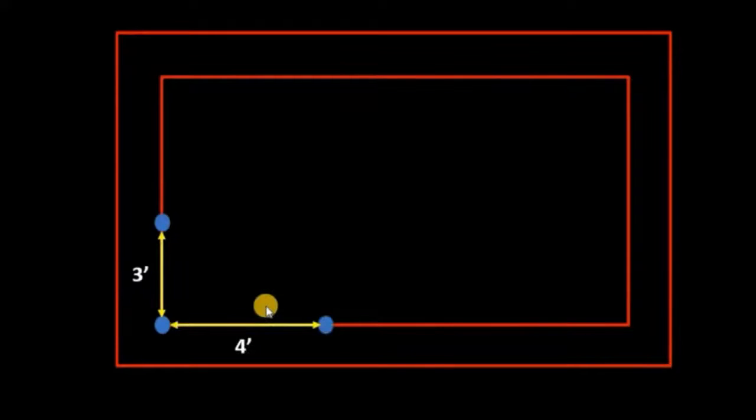And to check our angle, we can measure between those 2 points. Now if this is 5 meters, give yourself a pat on the back. Great job. If not, don't worry. We can adjust one of those marks until we have a 90-degree 3, 4, 5 triangle.